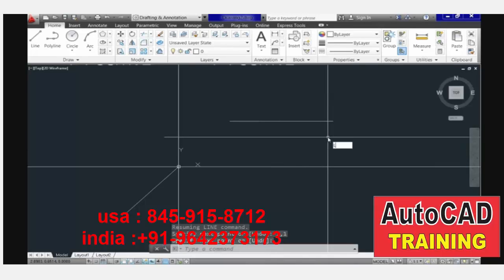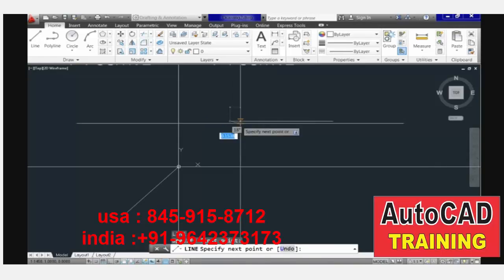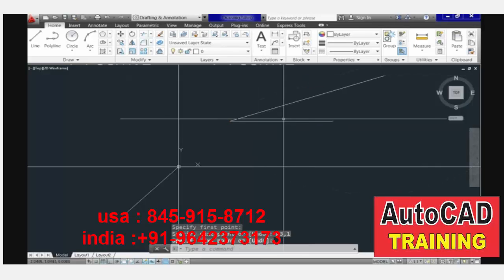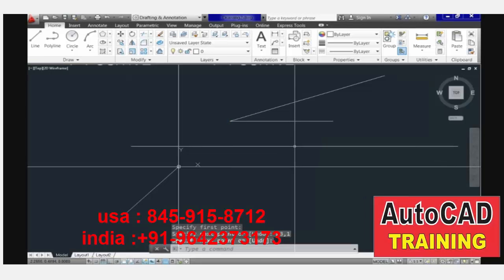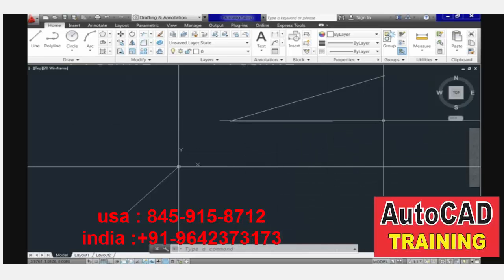But now let's use the same values and see how it works, not specifying the number symbol. You see, I used the same 3, 1, but a very different result. Why? Because by default, after the first point, AutoCAD switches from absolute to relative.